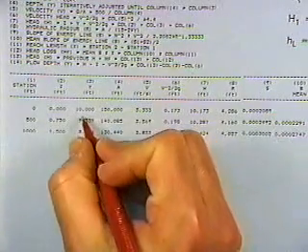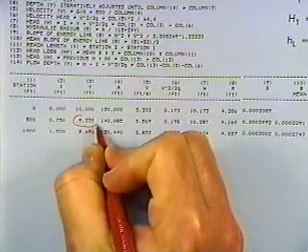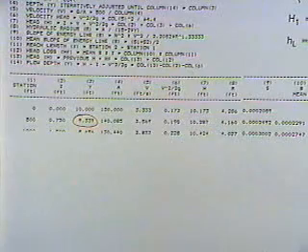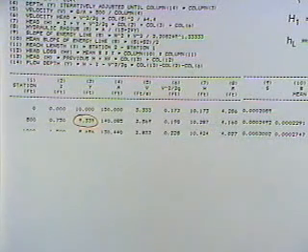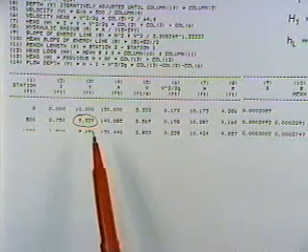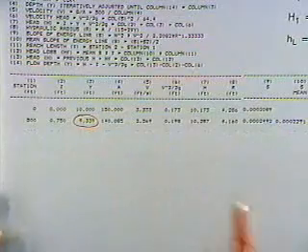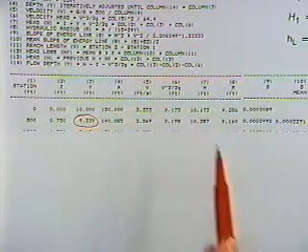And so what I'll do, I've got to assume a number right here in your table. That's the number I don't know. And I know it's something less than 10 feet. As you go up the concrete channel, the depth decreases. And so I make a guess. And after I make a guess of the depth, then I can compute everything.